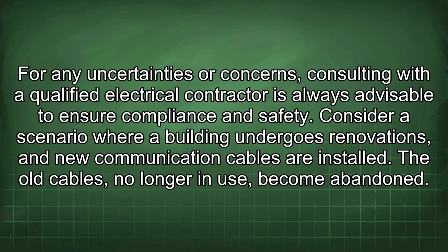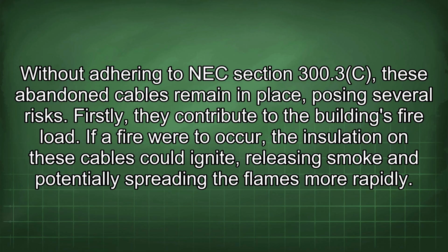Consider a scenario where a building undergoes renovations and new communication cables are installed. The old cables, no longer in use, become abandoned. Without adhering to NEC Section 300.3(c), these abandoned cables remain in place, posing several risks. Firstly, they contribute to the building's fire load.